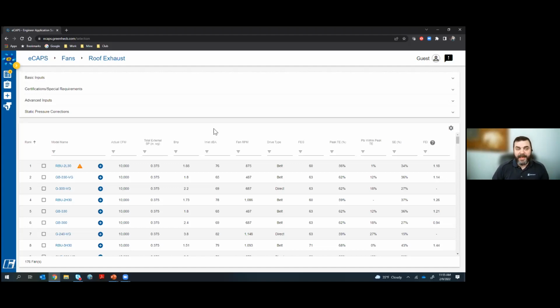But today, the best solution is to put in your max criteria, your highest CFM, and then look at that fan and say, can it go down that far? Sometimes the answer is a single fan can't do it. I have come across those applications. Sometimes you actually need to run 2 fans, but many times you can get there with 1 fan.